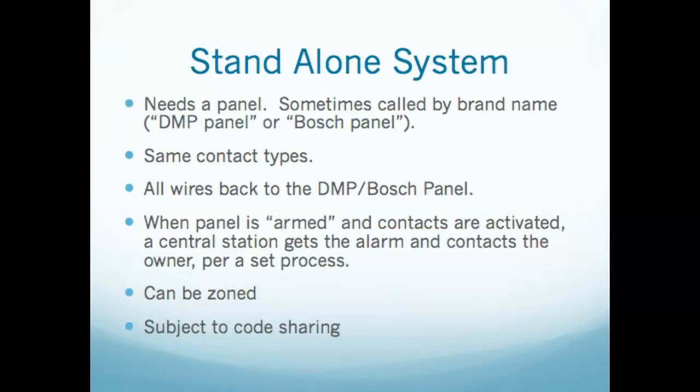We can put them through our access control panel using the alarm input boards in those panels and have them go right up through the same line as all of our door information, goes right back to the host. And we can monitor those alarms that way. So we'll know that only the right people are going through the doors because our badge information is coming from the host to the panel, back to the door, decisions being made. Now we know we have the alarm contacts going to that same panel, making decisions. It's all integrating with each other.